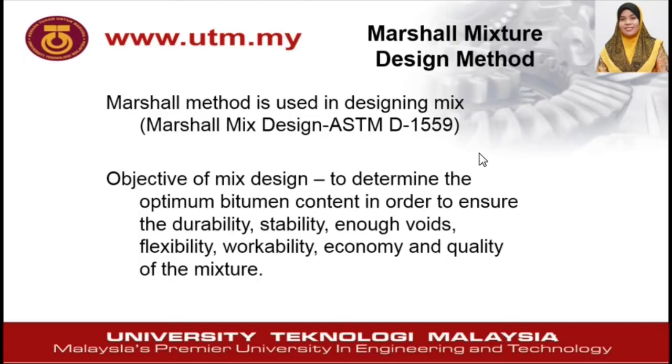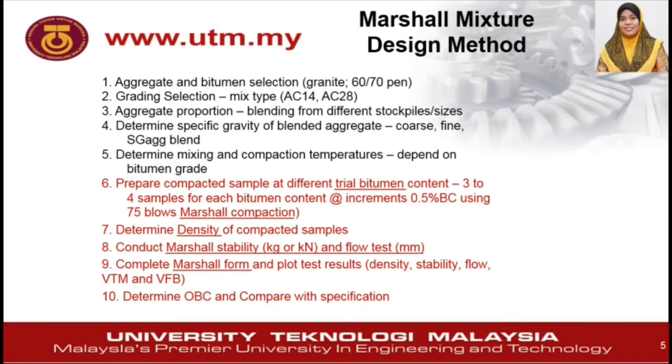So basically, what is the objective of Marshall Mix design? The Marshall Mix design is conducted to determine the optimum bitumen content in order to ensure good performance and quality of the asphalt mixture. As you can see from the slide, these are the steps that need to be taken prior to and during the OBC determination. Steps 1 to 5 are taken prior to the determination, which involve first, aggregate and bitumen selection.